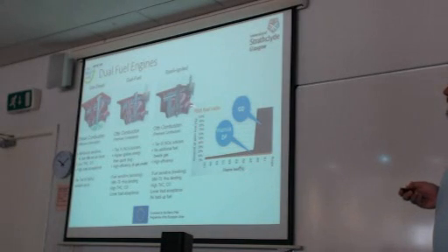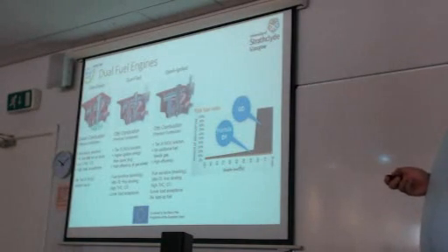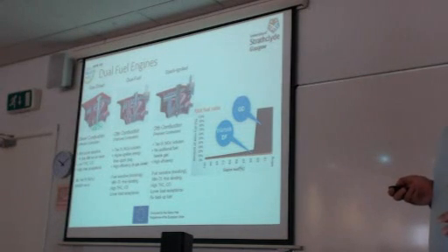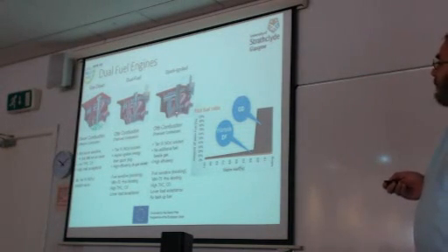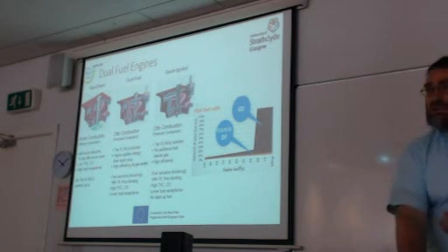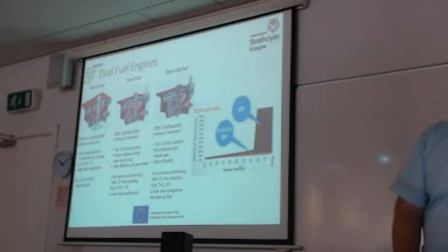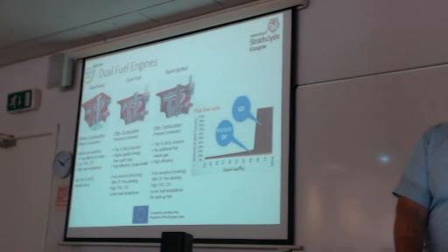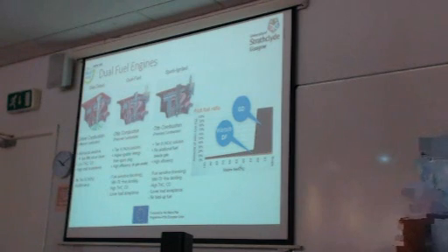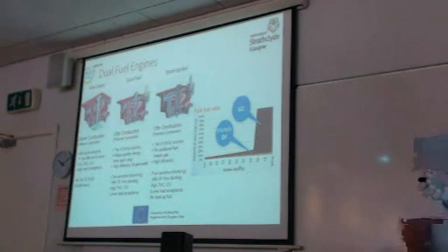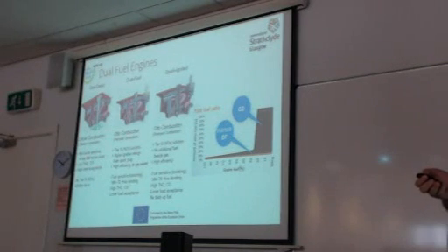In the case of gas diesel engines, you can see that the pilot fuel can be greater. And of course in the gas spark ignited case, we have only gaseous fuel, natural gas. So which are the advantages or disadvantages of the functionalities of the different types? For the case of the gas diesel engine, the combustion is not knock sensitive. You know what is knock, I expect, or not.